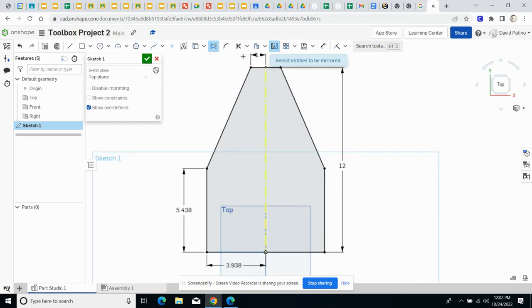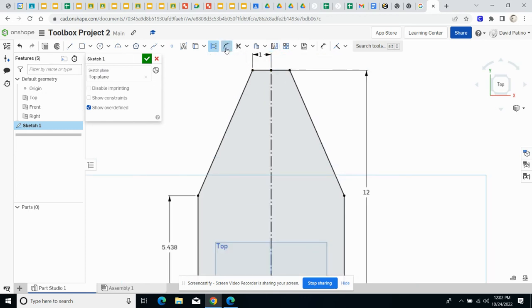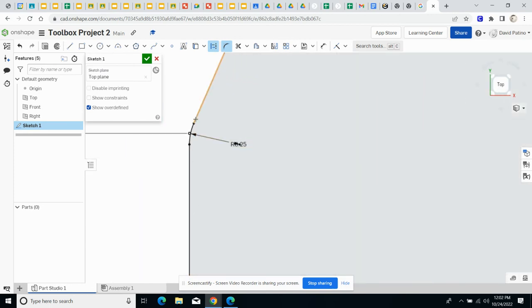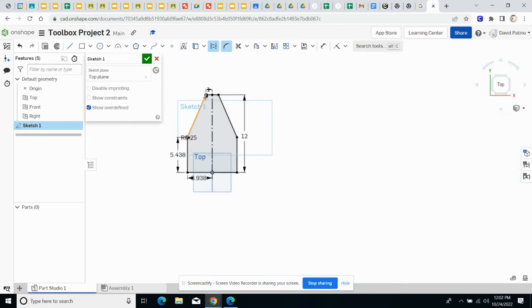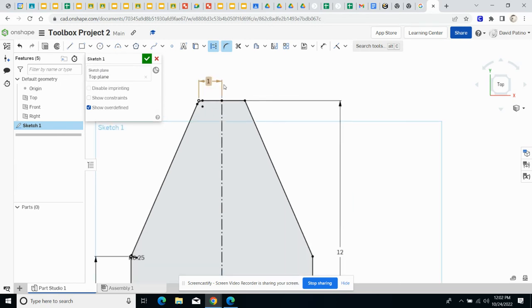We're going to create a fillet. The fillet is going to be between here and here. It already is saying 0.25, which is a 1/4 inch. Yep, lock it in, enter, enter. And then we're doing a fillet between here and here, enter, enter. So 2 enters and 2 enters, and we get a small fillet there and a bigger fillet up there.